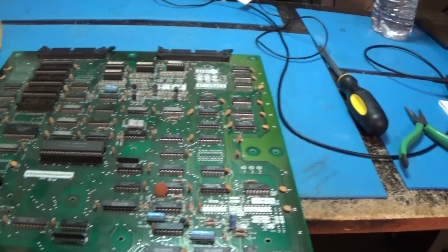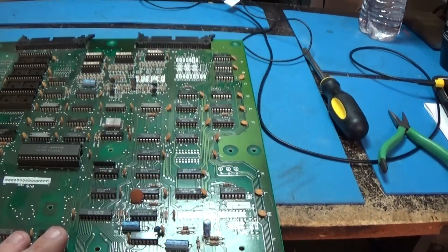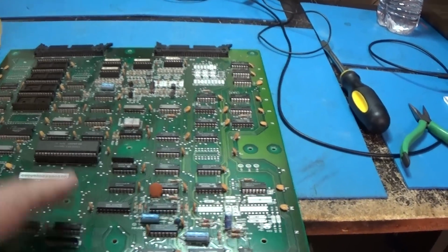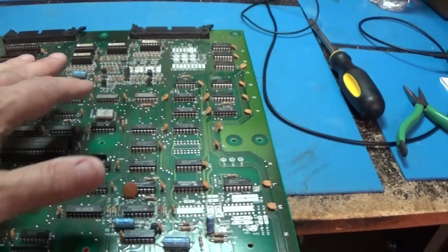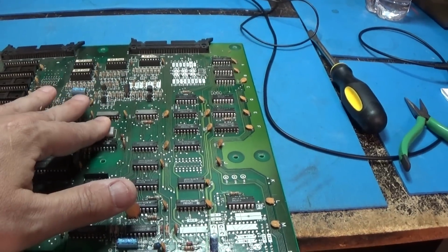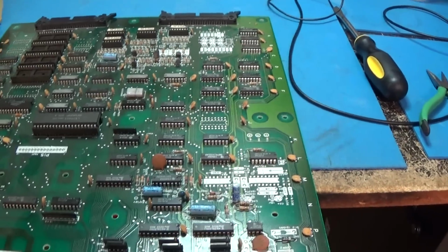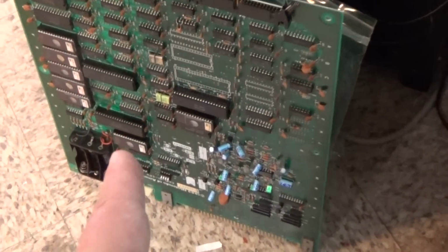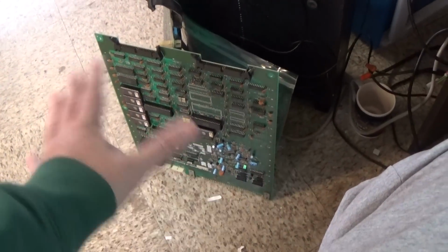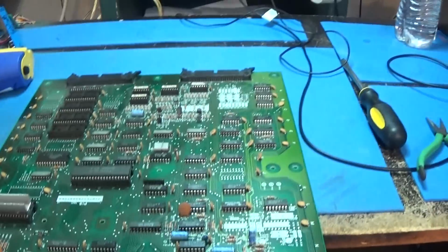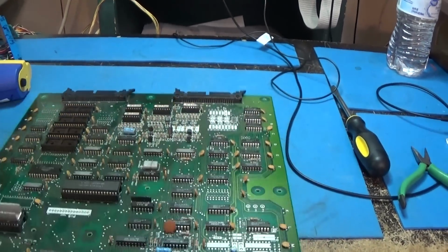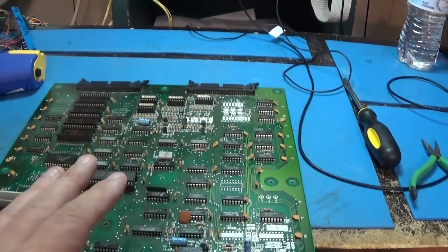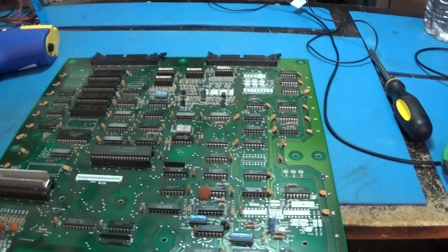It's my friend Todd's. It needs to be repaired, but it's the only thing that I can find that has an 8 megahertz crystal on it. So I'm going to use the 8 megahertz crystal off of this, and then I'll have to replace that, of course. But I'm going to use that to put onto that guy right there. That's that Punch-Out board. And we'll get the 8 megahertz clock working on that thing. And then I'll put this back, and eventually I'll have to replace this crystal on this Popeye board. But, yep, I'm going to use this guy to save that guy for now.